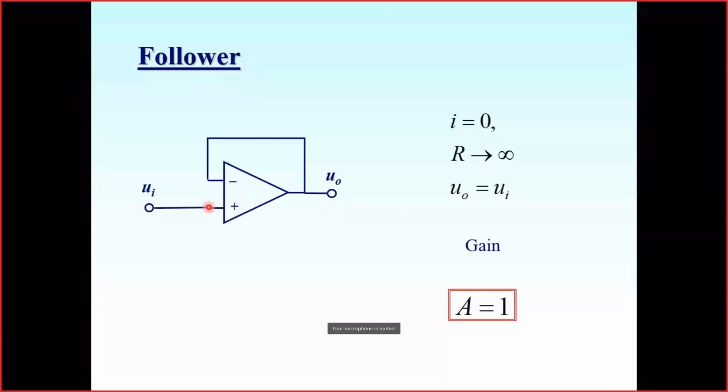So what does the follower do? It allows us to use some voltage source or signal source which is very poor in current, which couldn't provide a high current, could provide only voltage. There are plenty of such sources. All the normal chemical elements, electrolytic elements, which provide an electromotive force. Thermocouples also provide some voltage when they are heated.